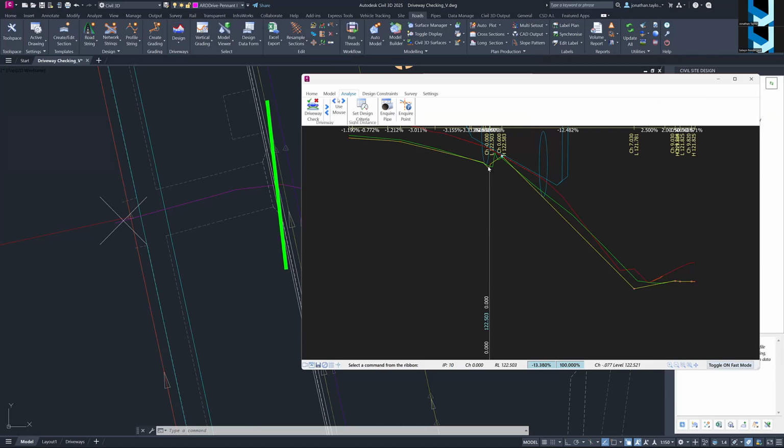In regards to how you resolve this, this is really down to you as the designer. I can't determine here what the constraint is that would necessarily fix this, because there could be issues with drainage, there could be issues with elevation, slopes, etc. But if we make design changes to our string, that curb will move up and down in elevation and position horizontally. The layback is something we can change.